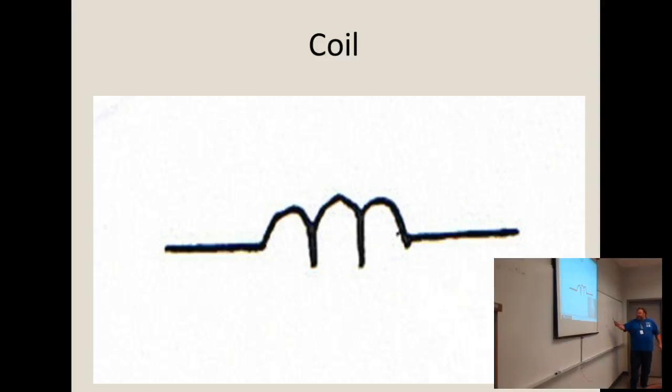The way to make this control it is to label it. In other words, if I label this X, coil X controls any normally open or any normally closed switches. Label that. So if this one was labeled Y and this one was labeled X, this one would only control this one, not that, right?